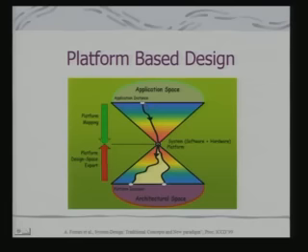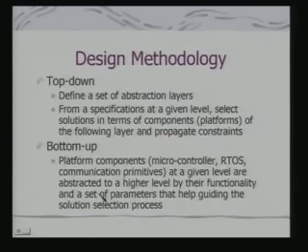So in a sense, your design process is not strictly a top-down design process. One way is platform mapping, that is, I am mapping to the platform, and the next thing is the platform design space exploration, that is, there are different possibilities in the platform design space, and from there we are mapping and trying to get the meeting point here. So this is the basic philosophy of what we call platform based design.